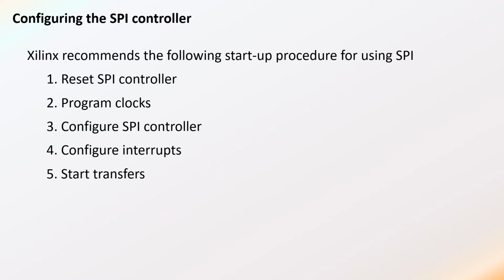Then set one of those status bits that we talked about, and then you can additionally make that status bit create an interrupt. Or same on the transmit FIFO. Maybe you want to be alerted when the transmit FIFO has only got 10 locations left. You can set a value to compare to the overall FIFO depth and alert you when there's only so many data points left in the FIFO. So configure the SPI controller for the application you have in mind.